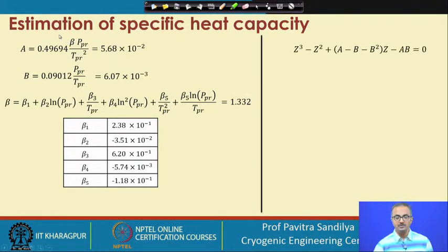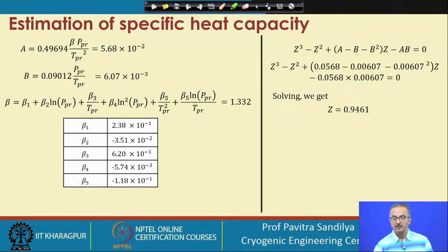So, now we come to the solution of this particular expression Z. We shall be using this value of the compressibility factor, and when we put this value of A, B, etc., we find that we get this value of Z here. Now, please understand, this is a cubic equation. We have not shown the details of the solution of this cubic equation of state, but there are 3 solutions here, and if you do this calculation, you will find that the 3 solutions may come to real.